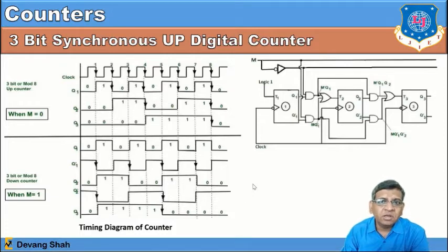So here triggering has its own importance, where it's always with the application of logic 1, it will trigger the output, right? So triggering the output means if the previous output is 0, this time it becomes 1. So it's continuously inverting the waveform.